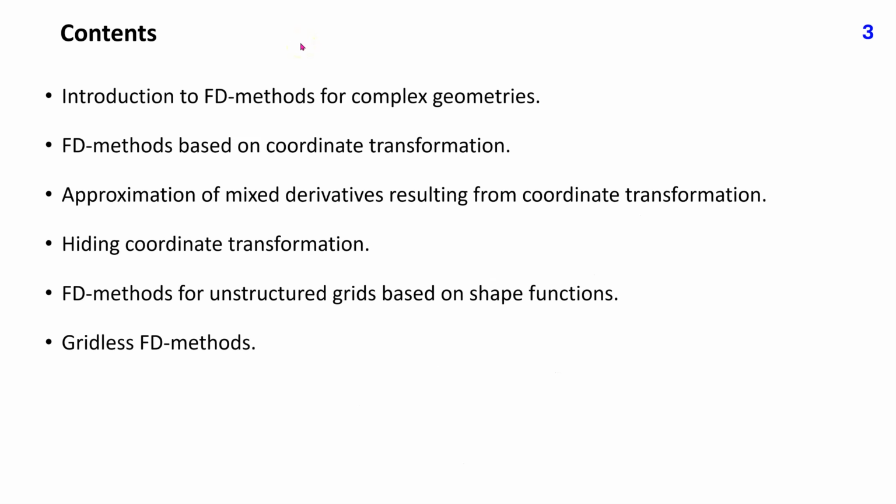Finite difference methods are usually used only for moderately complex geometries and either with structured or block-structured grids. Most published methods use coordinate transformations to convert the Navier-Stokes equations from Cartesian to non-orthogonal coordinates, but there are also other possibilities, of which we shall mention one.